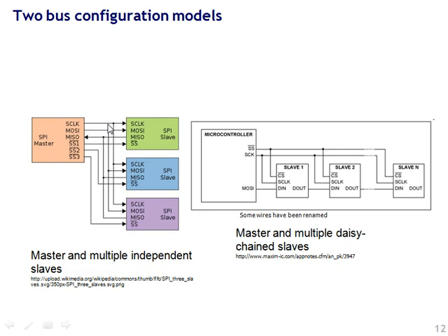And they're all sharing the same serial system clock, the same MOSI and MISO, and that's all clearly wired ORed. But the slave selects, you need 1 line for each slave. So master-slave relationship exists. What does that mean to me? It means the slave cannot take over the bus and communicate with another slave on its own. That's what that means.